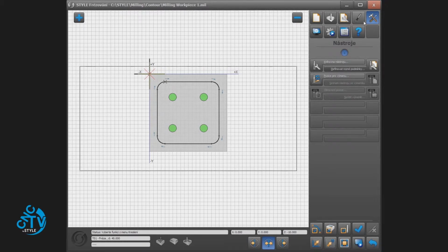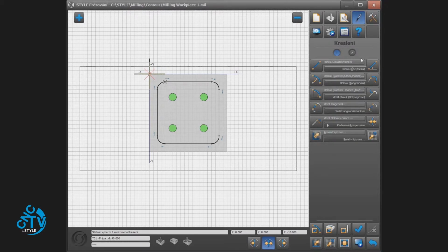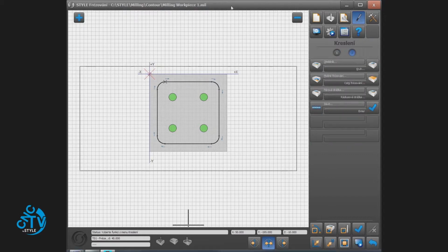After you have selected your tool, you go to Draw. With Draw you can draw all the milling and drilling operations into the workpiece. You can have facing, threading, slots, circular pockets, rectangular pockets. You can draw milling contours with lines, arcs, tangential arcs. You have radius compensation, of course. All these options will be explained in more detail in other movies. So if you want to know more, please select one of the other movies.